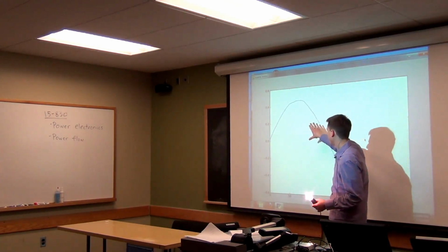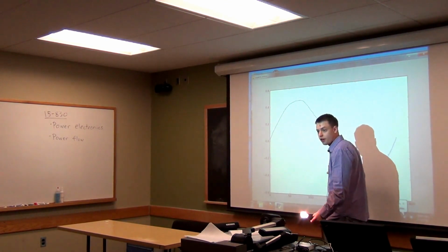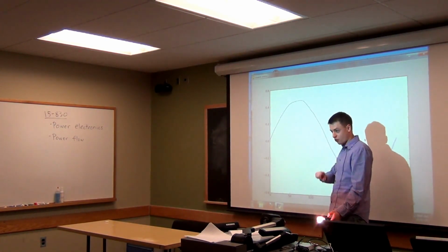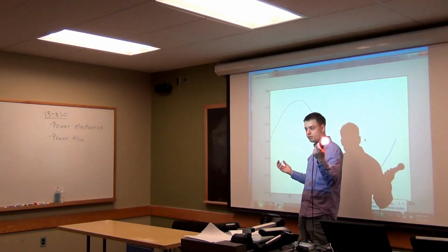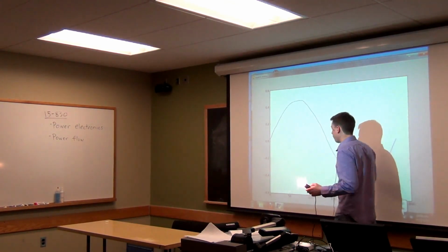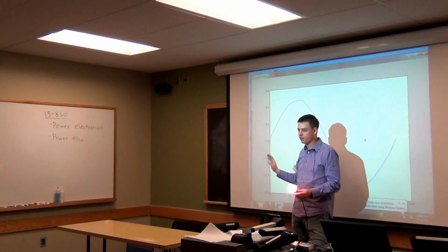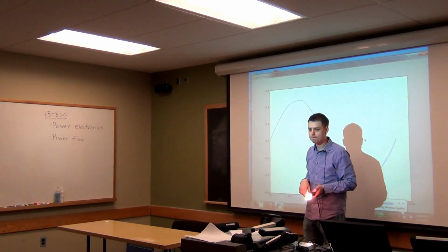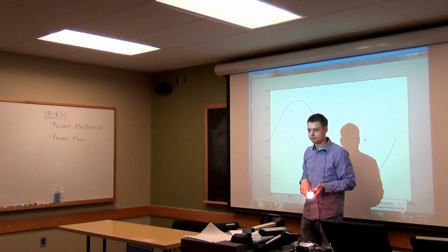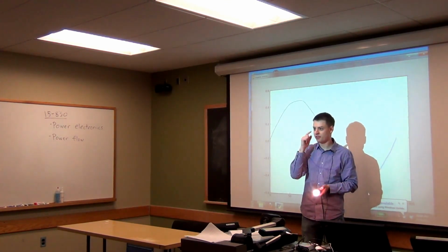Because if you look at the root mean squared value of the current times the root mean squared value of the voltage, that would actually be the apparent power of this thing. But because it looks like it's pretty well in phase, the voltage and current are pretty well in phase here, this is about 40 watts of power this is consuming. Does all that make sense? Yeah, there's a question there.